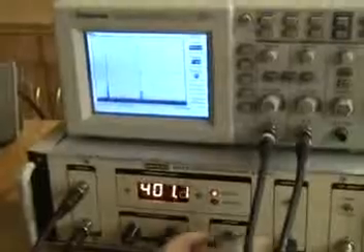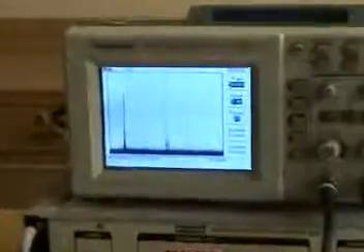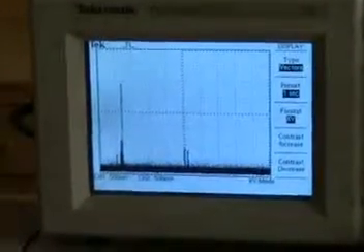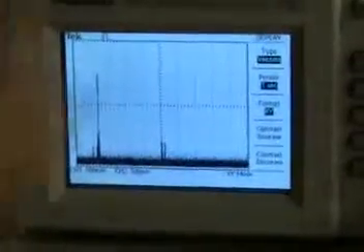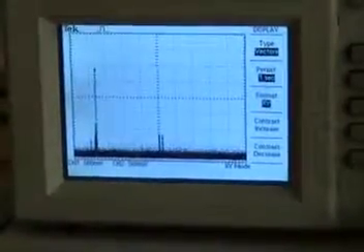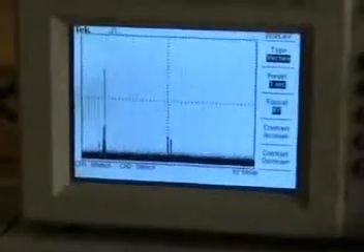Now as you have seen, if we were to put a video filter, suppose, now you can see this is the graph of the spectrum analyzer, and this is nothing but AWGN noise. This is additive white Gaussian noise of a spectrum, and any signal below this noise floor will not be identified by the spectrum analyzer.